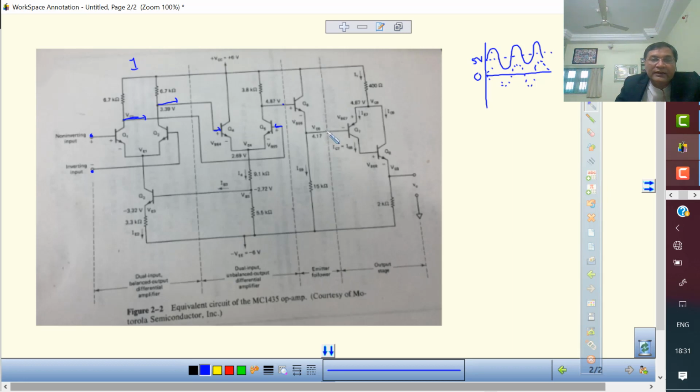And then the output you are getting here, you cannot use directly with your device. Suppose this is the output, already amplified. Suppose you connect it to a speaker, this is your speaker. You connect this point here, and one is grounded. So there is some problem. What is that? There may not be matching with the input of this one.